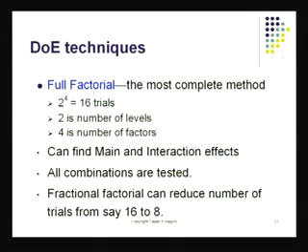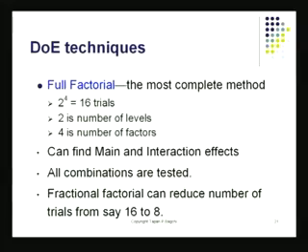And then of course there are many different techniques, and one of the popular techniques for doing experiments is to use the full factorial design. This is the most complete technique. It can find the main effects and also it can find interactions. So both of those things can be found if you use full factorial designs. All combinations of the different treatment levels can be found by doing the full factorial trials. That is there. But if these experiments become too many, I have to use some other method which is called running a fractional factorial run, and that I'll show you. Once we get into that, I'll show you how we come back from full factorial design to a partial factorial design. And that's actually a pretty efficient way to find a lot of information without having to run all the different 2 to the power k experiments, which is like the full factorial design.